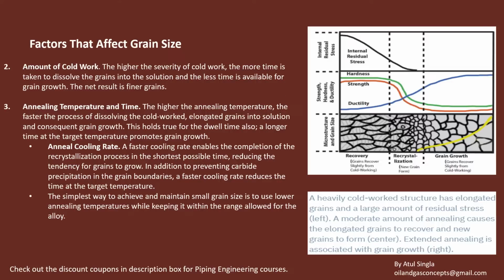At the same time, if we look at the second part here, when we are doing the cold work, there will be a lot of residual stress at the boundaries, so we have to perform the annealing process to release these stresses. Now in this part, there is a change in crystallization, the structural change of the grain, when we are doing a moderate amount of annealing, within the temperature limits and within the time period specified in various standards.